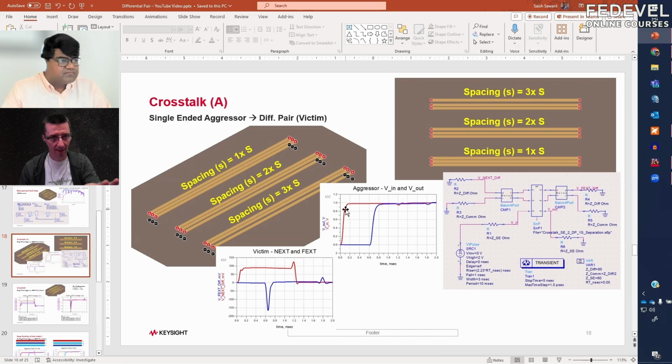I will interrupt you. When we have a look at this schematic, I just would like to be sure everyone understands what we see. The biggest part in the middle, that's our PCB layout, correct? Yes, that's the EM extracted S parameter data. That's the PCB. So when someone would like to do simulations of their board, one of the ways this is done is, when they finish layout, they create this S parameter file of the PCB, and then they can connect these signals there and see how the results will look when these signals flow through their custom PCB.